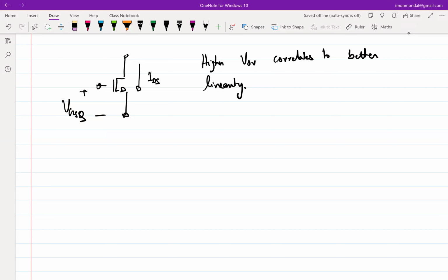For those of you who have taken device courses, you will see that the more involved model of the transistor has multiple variables, right? We do not want to go into those complicated equations, but you can appreciate that for short channel devices, the current voltage relationship is not square law. It's not VGS minus VT whole square. That's because it's something times VDsat, right?